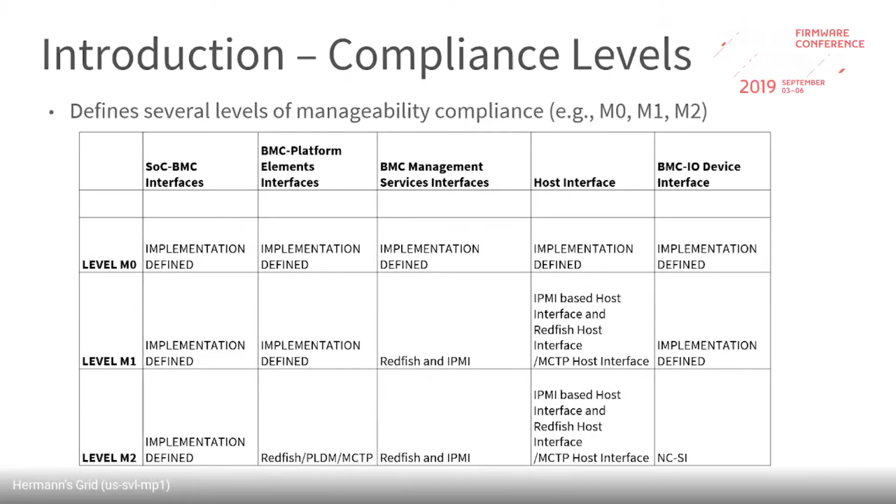Currently, for the IPMI-based host interface, we can't use KCS or BT or any other LPC mechanism, because the ARM-based SOC host doesn't have any of those interfaces. So SSIF is the one which we can use for now. The rest of the interfaces are implementation defined at this point for level M1.